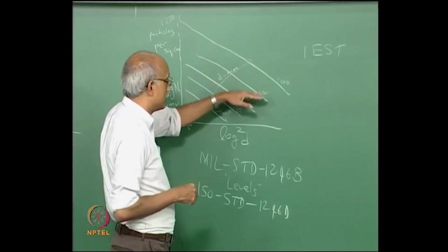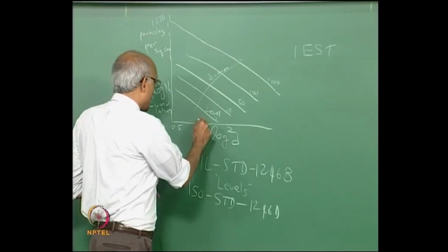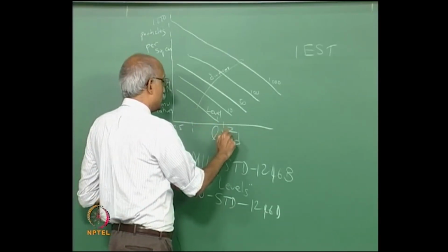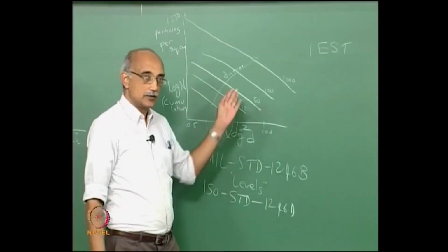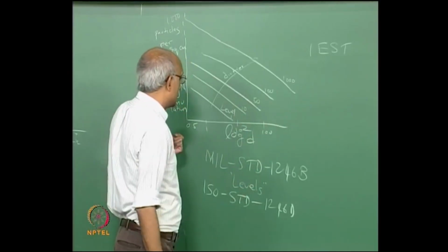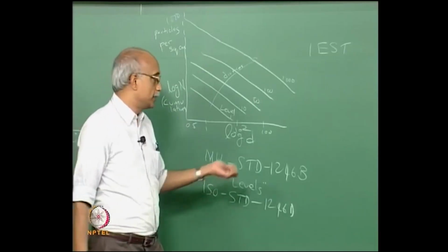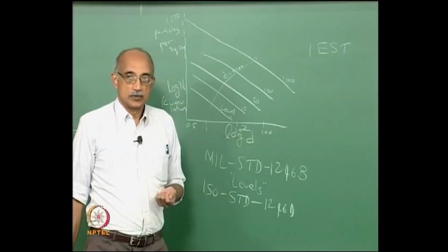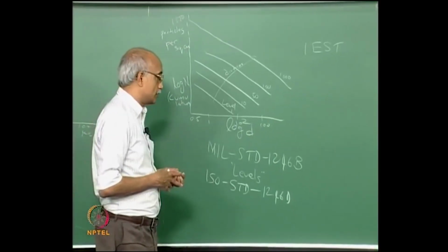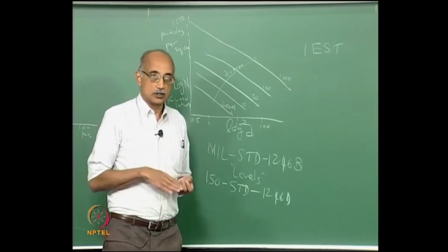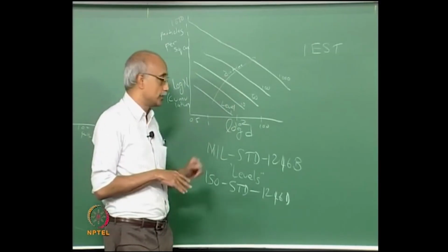And since the slope is fixed, once I say what the count is at 0.5 microns, you can actually calculate what the corresponding counts would be at 1 micron, 10 microns and 100 microns and so on. And again, given the slope of the curve, if I have 1000 particles that are half a micron and larger, the probability is by the time I get to 100 microns, the number will be very, very small, because again when we talk about naturally occurring contamination on a surface, there is a linear downward slope when you plot it